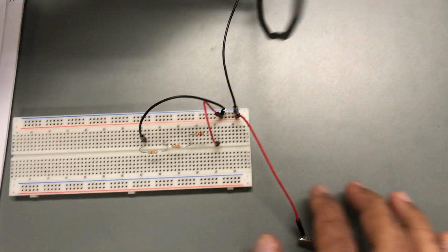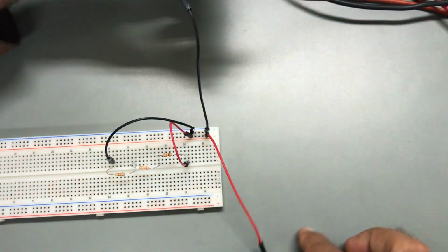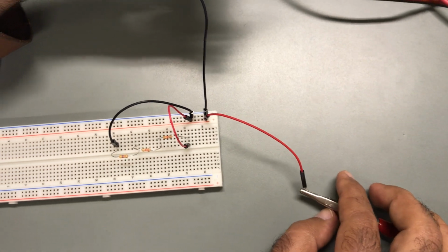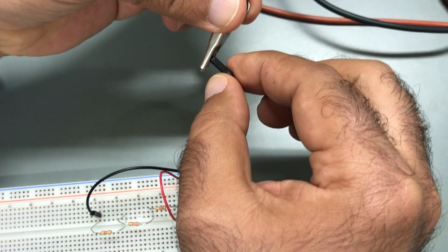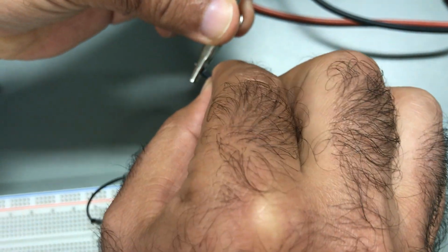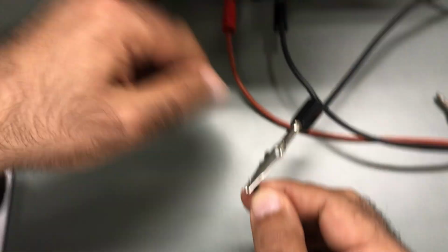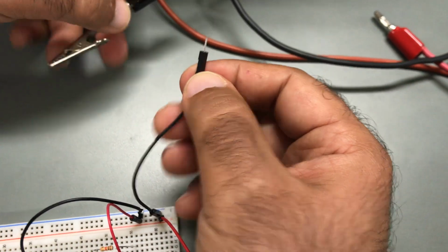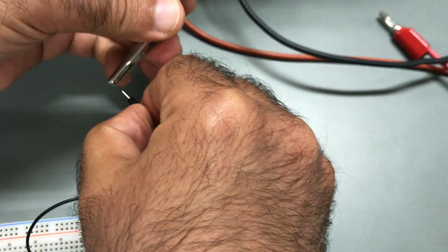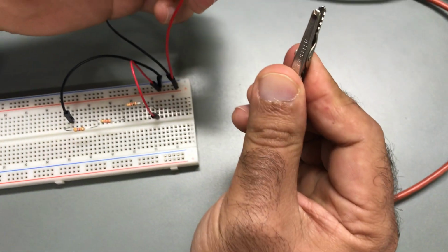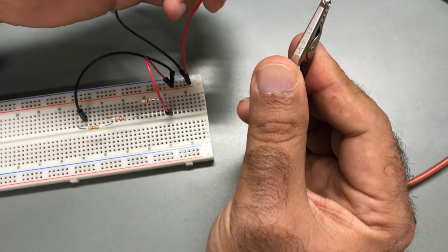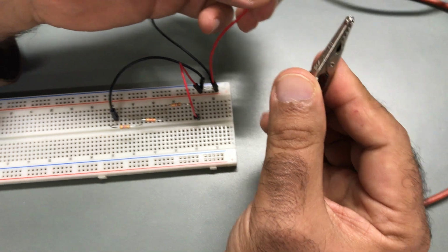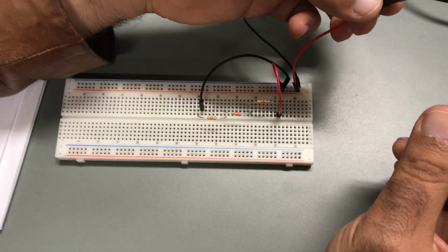This is my power supply. I would like to connect a meter between these 2 points. I would like to measure the current here. So I will disconnect this and put an ammeter here. I will turn it off, then disconnect this and connect the ammeter between these 2 points, or I can disconnect this and put the ammeter here, whichever is easier for you, but pay attention that the direction of the current will be changed.